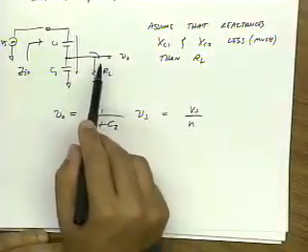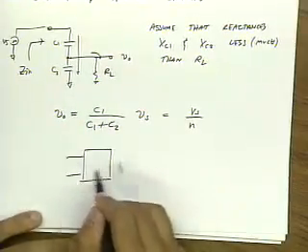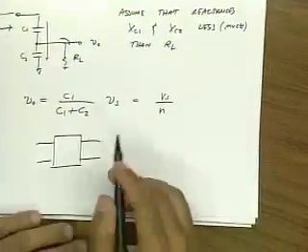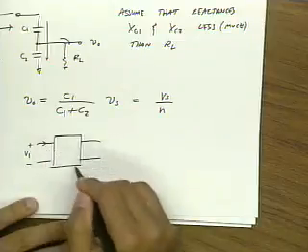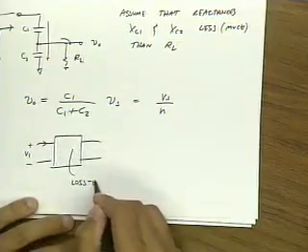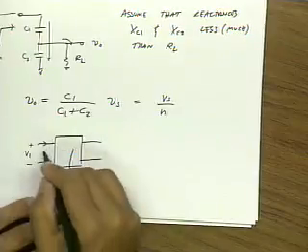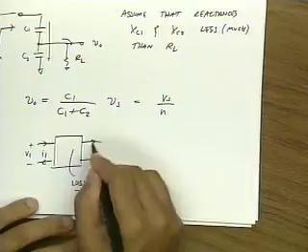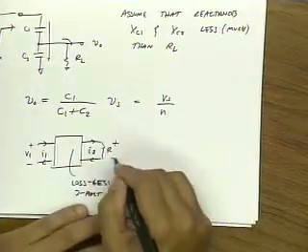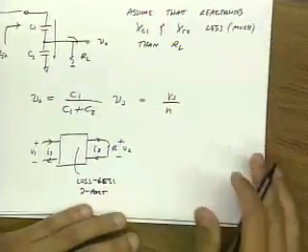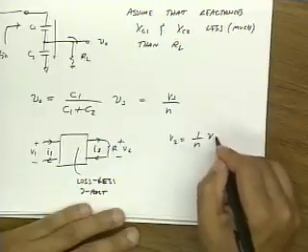Anytime I do a voltage transformation, I also do a current transformation. Let me just review that with you guys. Let's assume that I have a lossless two-port. And this is V1 and this is V2, I1, I2. And let me assume that V2 is 1 over N times V1, right?